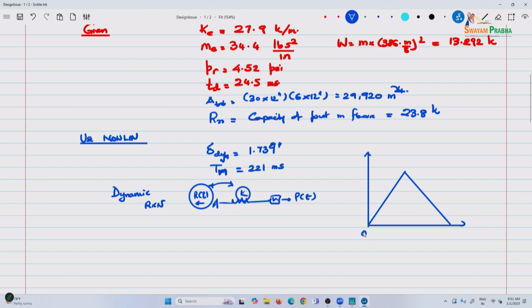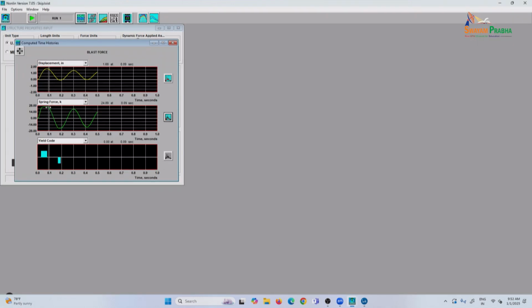the period is there. So this is 0, 70, and at 140 back to 0, and the peak value here is, so let's go and look at that. So the peak value here is about 26.2 at 0.07 seconds. If you're not able to read that, that is 70 milliseconds, 26.2 kips, and it goes back to 0 at about 140. And there is also, if you see, a rebound effect. So anyway, we won't focus on that for now.